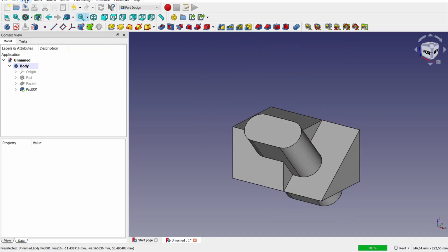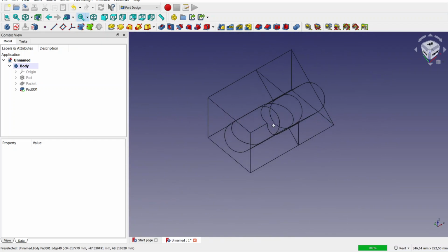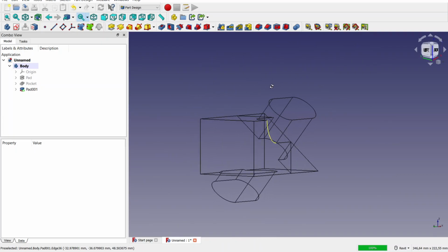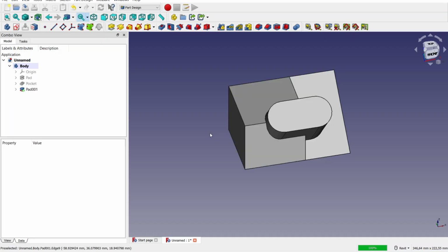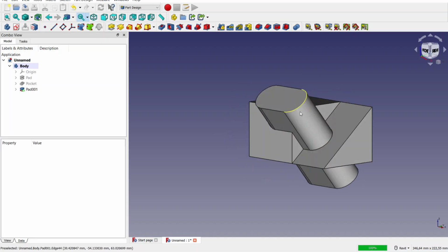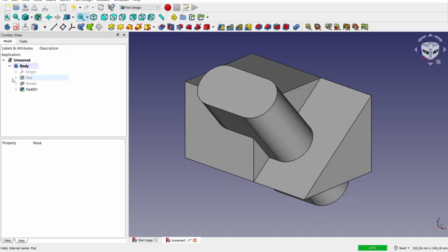If you go into View, Draw Style, Wireframe, you can see that the inside of it is empty. In other words, it created a clean, solid model. Now a shortcut for that would be V3. I'm going to use V7 to go back to the shaded with wires mode, because that's what I want to use. All right, now first let's save this file out as the original copy.